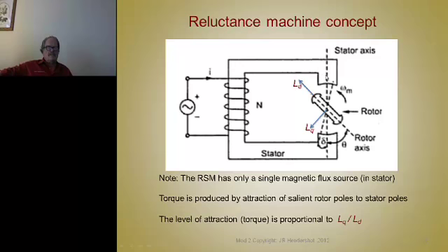All the flux is carried by this permeable core, very high permeability as opposed to air. So there's going to be a lot of resistance to the current buildup in this. The L over R is going to be a big number. We call that inductance the D-axis inductance.